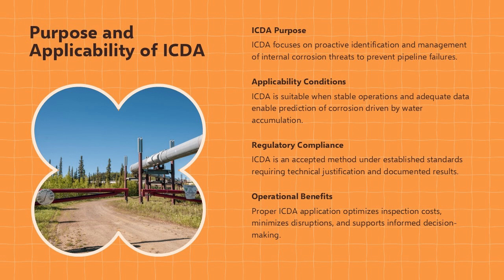From a regulatory perspective, ICDA is recognized as an acceptable integrity assessment method when performed in accordance with established standards. Operators must demonstrate technical justification, proper execution, and documented results. When applied correctly, ICDA enables operators to meet integrity management requirements while optimizing inspection costs and minimizing operational disruptions. It also provides a defensible framework for decision-making related to maintenance, mitigation, and reassessment intervals.